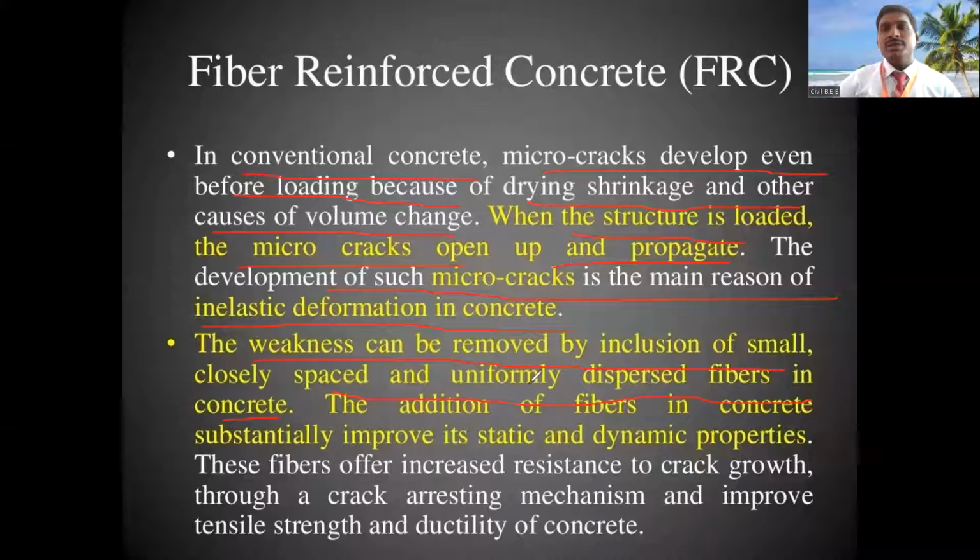Why? To remove the cracks developed on the surface of the concrete due to shrinkage, which we will minimize by using these fibers. In addition, with fiber concrete, sustainability improves, and the static and dynamic properties also improve. So these fibers increase the resistance to crack growth.